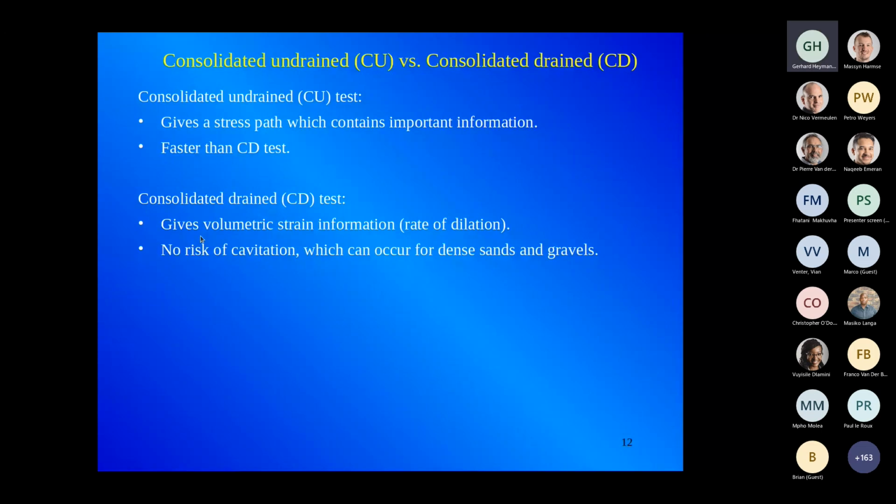Also, if you're interested in volumetric strain behavior, for instance, rate of dilation. Now, if you're using the Cam-Clay model or the NorSand model, rate of dilation is a very important issue. And that information you will get from a consolidated drained test. So that's the second case where I would recommend consolidated drained.